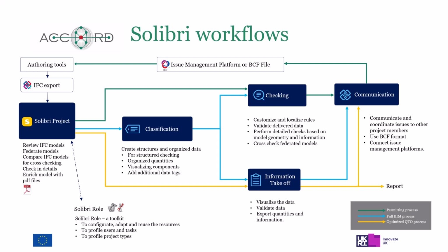A typical process goes through classification, where you can organize and restructure the data and even add additional tags to your building elements. You can run through the checking, link the classification names in checking, so you are checking elements with a certain classification tag or name. And you can collect information, takeoffs, the quantities, using the structured data in there, and communicate the results, if found any, through the BCF tools to the author again.